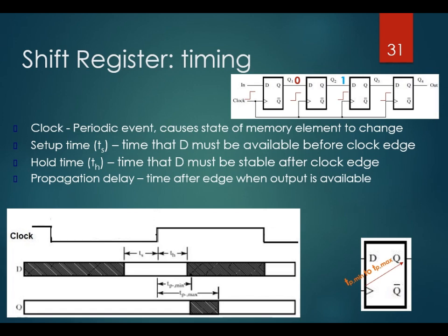As you can see here, a shift register has a very simple connection from one flip-flop to another. However, when it involves flip-flops, timing analysis is normally very important. For this example, timing analysis for a shift register is important to ensure the data is correctly shifted and stored at the appropriate time without error, especially when dealing with clock signals, setup time, and hold time. For example, currently we have bit 0 at Q1 and bit 1 at Q2. So timing analysis needs to be done so that it fulfills the setup time, hold time, and timing criteria, such that the shifting will happen successfully.